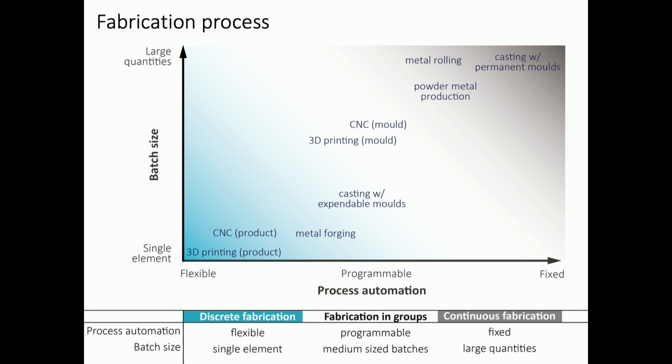And like Lindsay, the rationalization definition guy, mentioned, it's not feasible to have complete uniformity in joints in freeform geometries, but when you fabricate in groups, if the threshold of the joints that are the same is below a certain limit, you can make up for the cost of the joints that are too different from each other. Because obviously discrete fabrication costs more than continuous fabrication. So it's all about finding a limit.